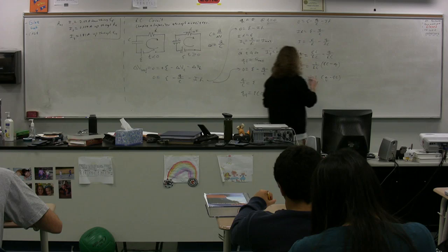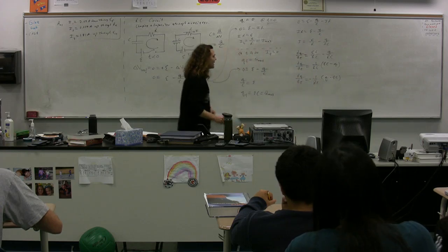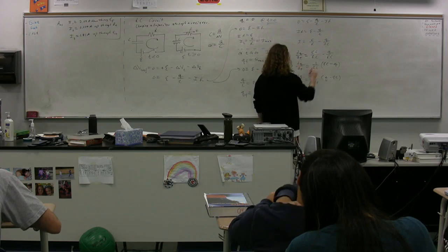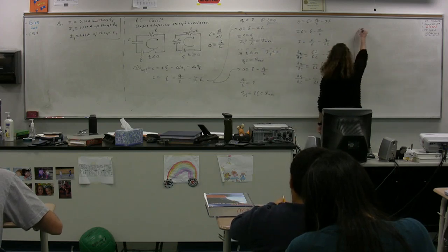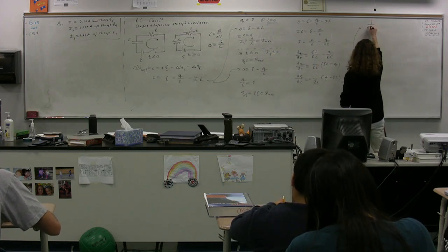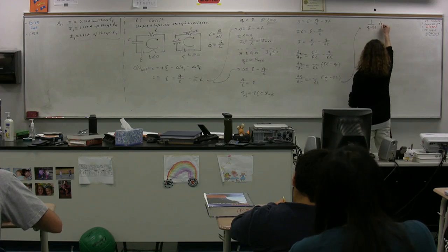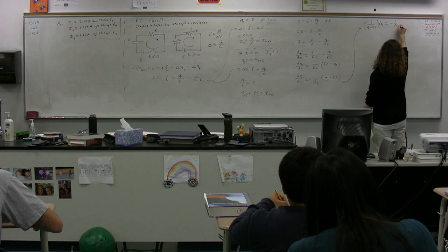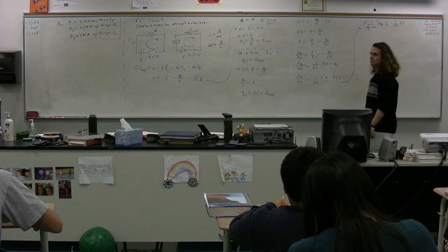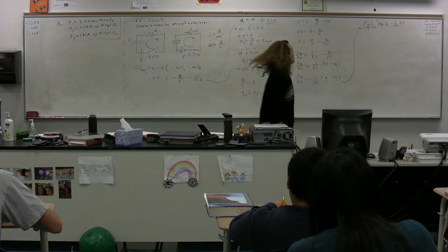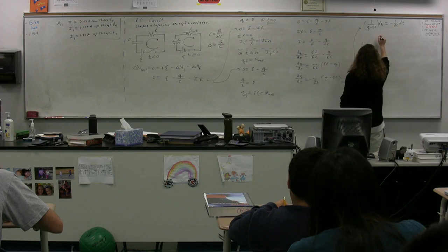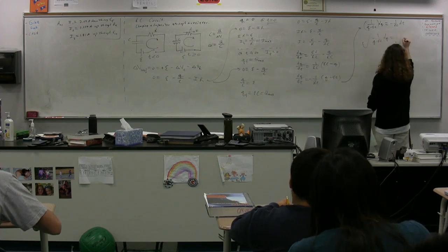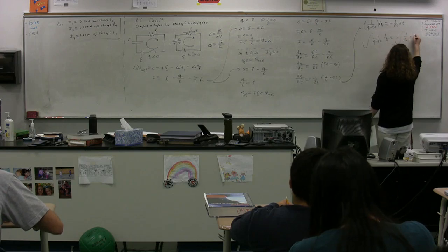So this particular step, multiplying through by a negative. Now, I'm going to bring the dt over to the other side and the Q minus EC over to the other side. So what we get here is 1 over Q minus EC dq is equal to negative 1 over RC times dt. We can now take the integral of both sides. We get the integral of 1 over Q minus EC dq is equal to the integral of negative 1 over RC dt.